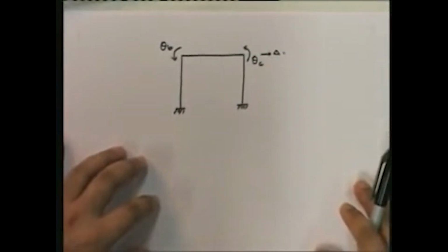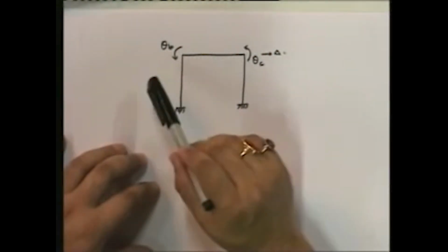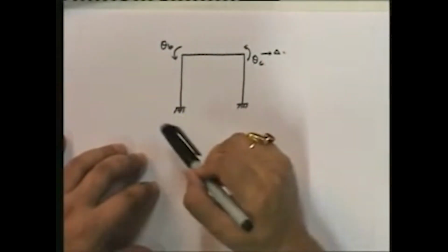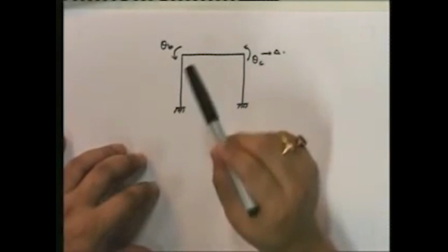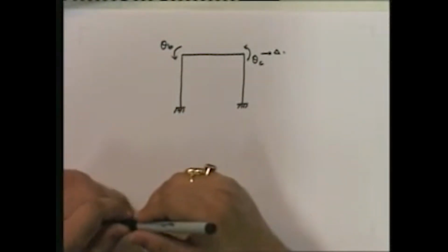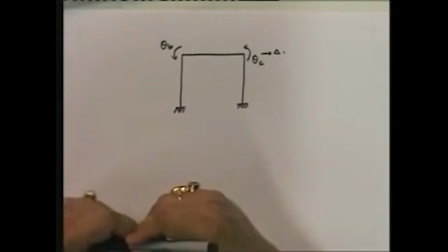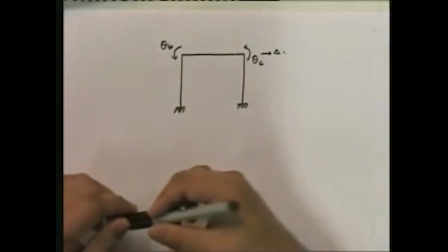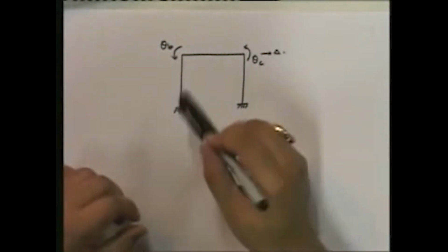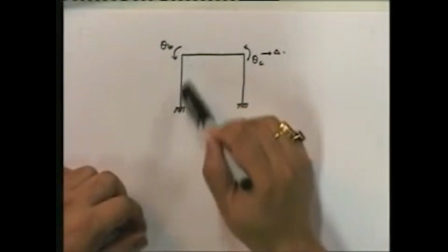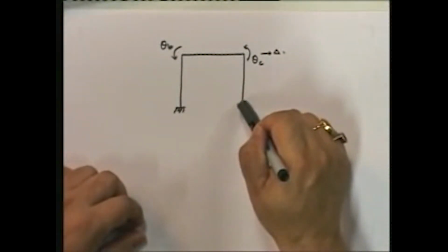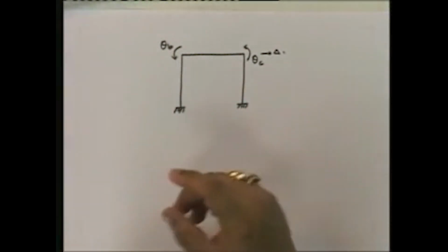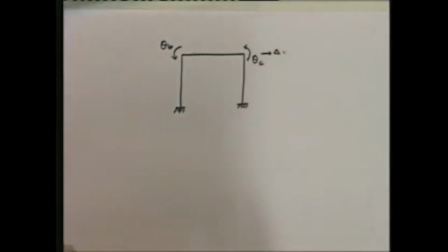Now I am going to introduce some concepts. Before I write down the slope deflection equations, I have to be able to relate these to the member end deformations. So I am going to start a new procedure by which, given each degree of freedom, I find out how the displacement occurs, so that I can always write down in terms of that displacement what the member end displacements are. Then when I take all 3 of them together, that becomes the sum total.